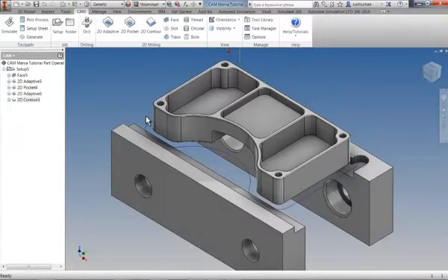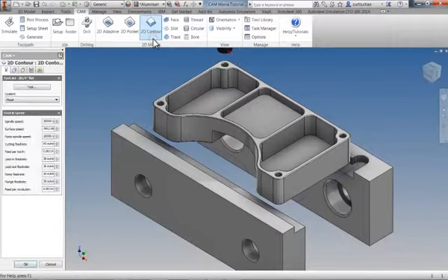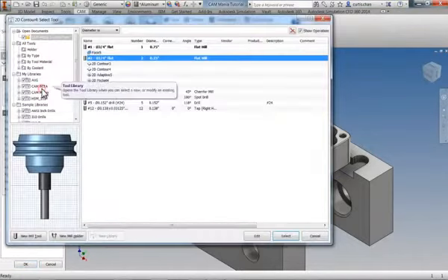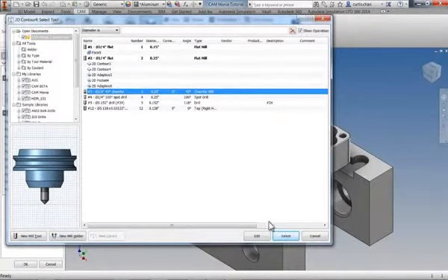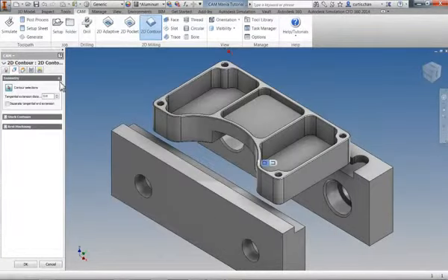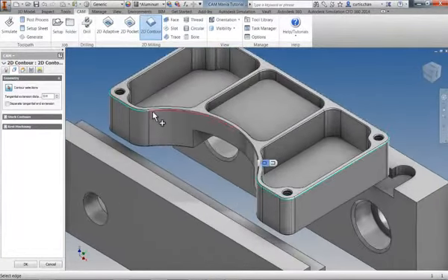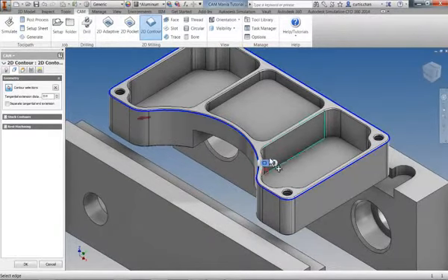complete. Next, we're going to break all of the sharp edges on this part using the chamfering option of the 2D contouring operation. Open the tool library and select our 1/4 inch chamfering tool. Activate the Geometry tab and select the bottom edge of each of the chamfers.